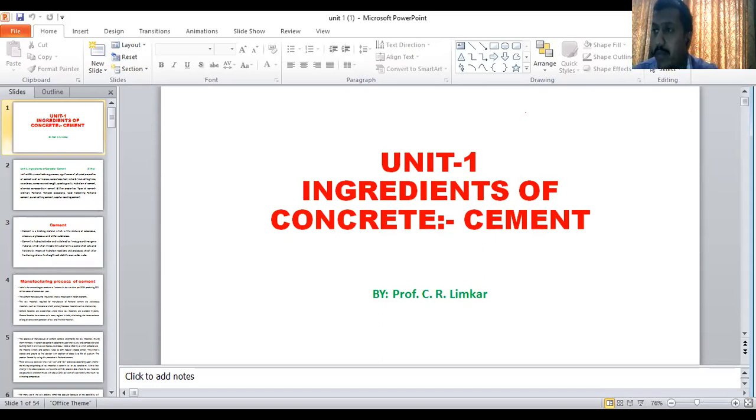On a building, as you know, there are different types of loading acting: dead load, live load, impact load, wind load. I think you have studied this part in your design of steel structures in diploma, correct? IS 800 2007 and IS 875 2000, though you are using the older 1975 version. So you know what kind of load acts on a structure, correct? It may be the dead load. Can you give the best example of dead load? Self load, sir. Yes, the self weight of your building.